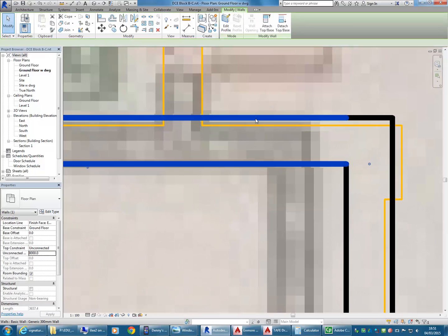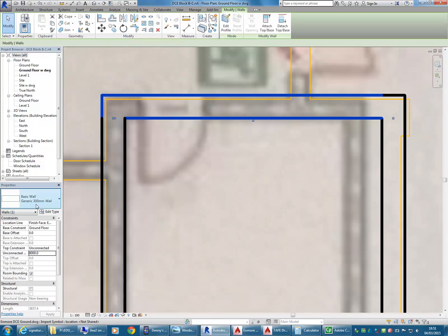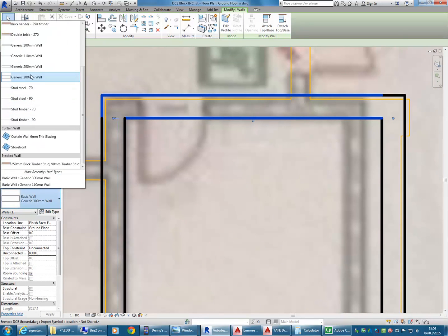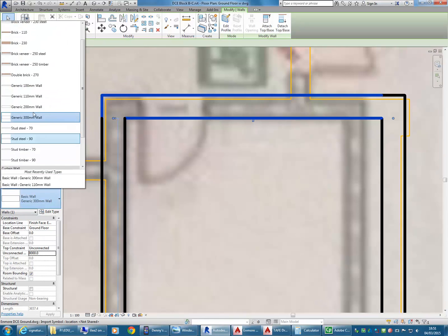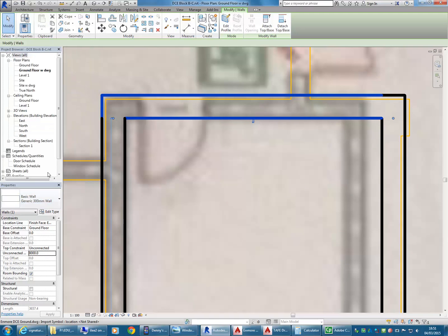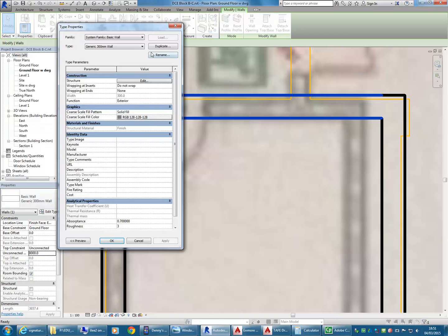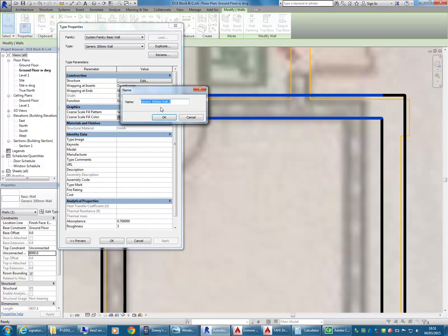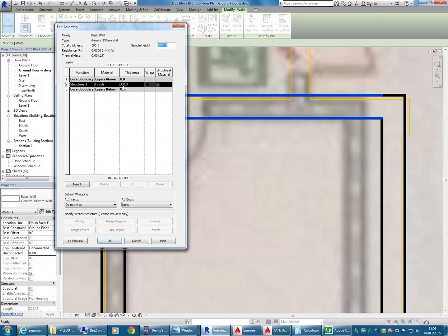So I can tell there these walls are too thick, but I do have a 250mm wall, I hope. Oh, no I don't, sorry. So I'll make one. So again, just following that generic wall type, I'll make a new 250mm wall. Why is it 250 and not 240? Well, it's 230 and then there's render both sides. So, yeah, close enough to 250.